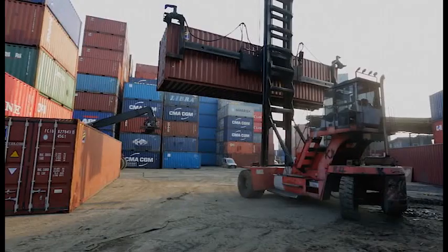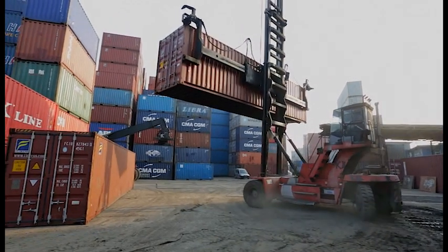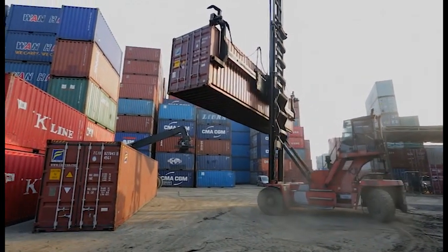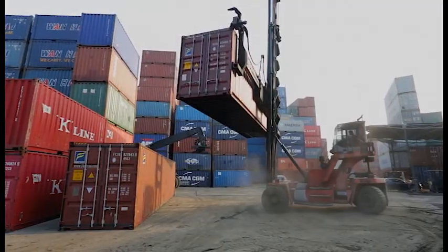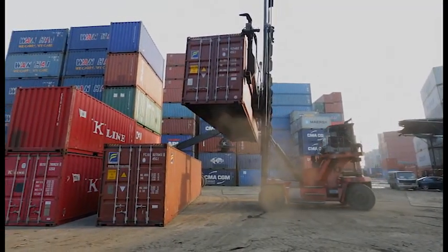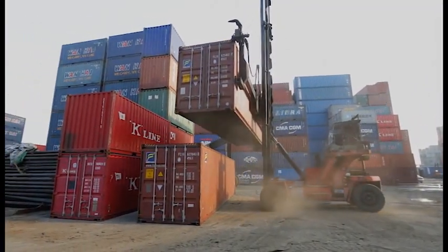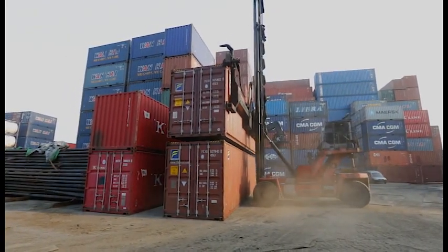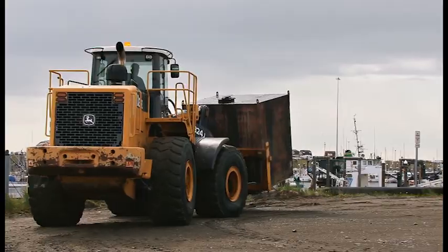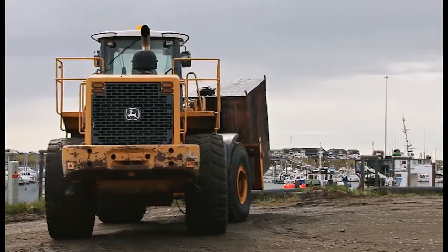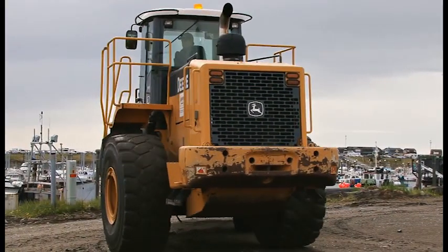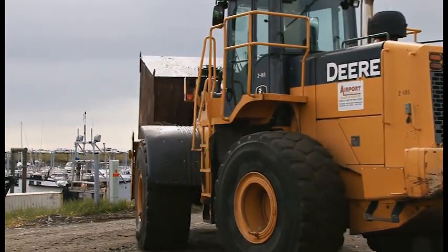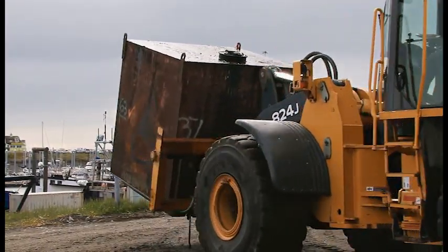Attachments. Forklifts often use different attachments in place of traditional forks. Attachments increase the versatility of the lift, but can present important safety considerations, including stability, capacity, and visibility. Potential hazards include overloading, tipping, and falling loads. Operators must be trained in the proper use of attachments before using.